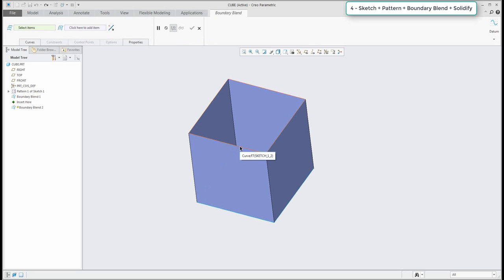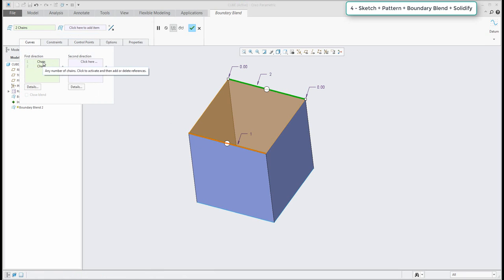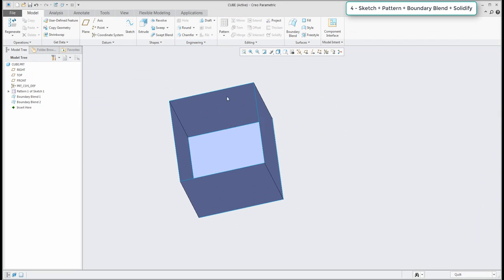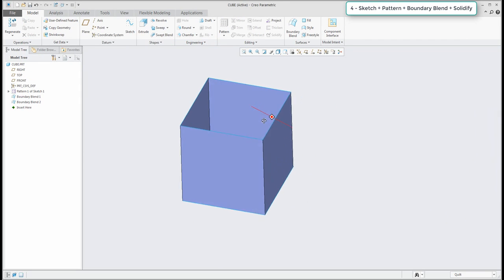surface, but you don't want to select the whole curve or whole chain. So I will remove it, and you can select the right mouse button. The system will select only one curve, and then hold down the control button and again left and right, and the system will select the curve. And over here in the menu you can see that you have 2 curves. So it was good. And another possibility, or I will do it the same.